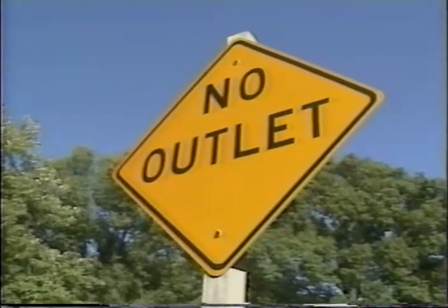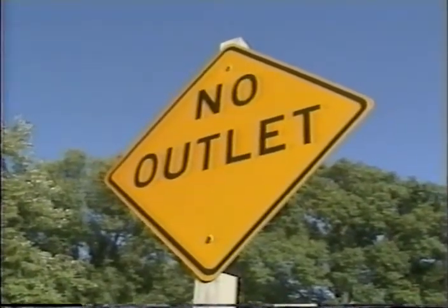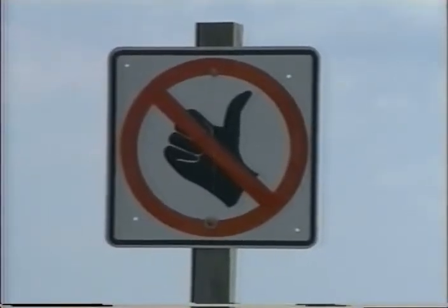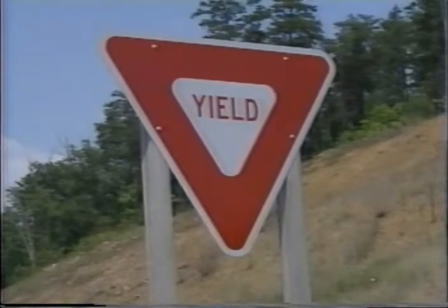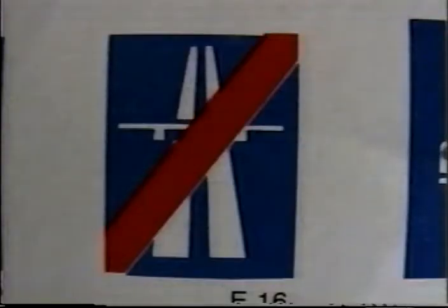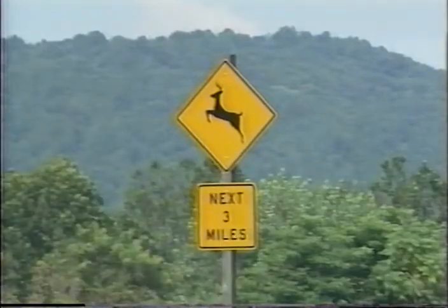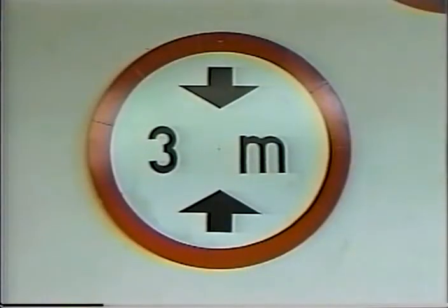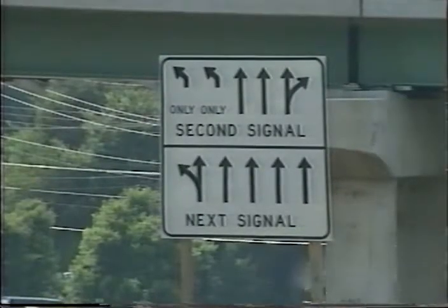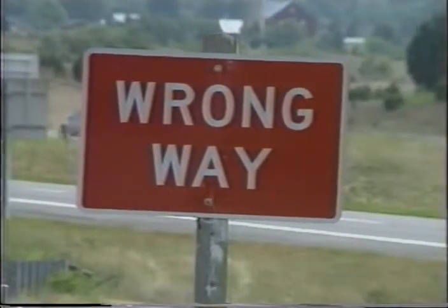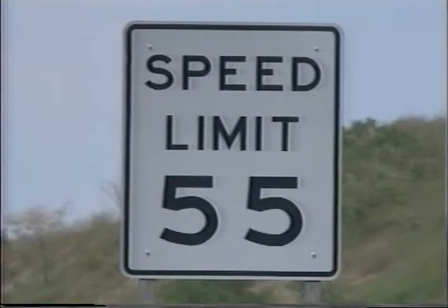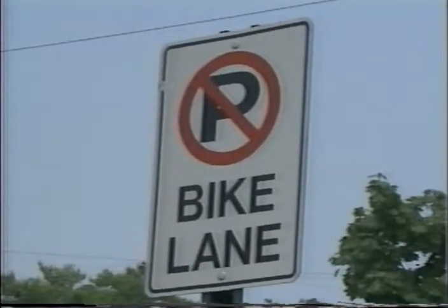In this presentation, we have covered many examples of signs that are common to all three worldwide sign systems: U.S., European, and Latin American. We have seen patterns of uniformity as well as differences among the three systems which affect driver recognition of signs around the world. Sign functions common to the three systems are regulatory, warning, and guide. Regulatory signs inform drivers of laws which regulate driving. Typical of these are speed limits, turning movement regulation, and parking restrictions.